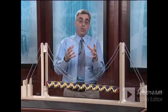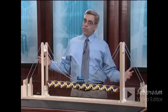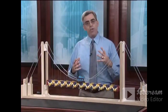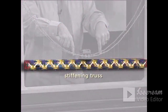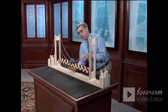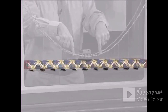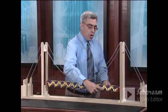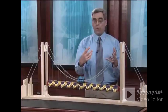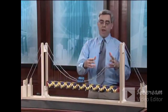The way we look at a structural system is to start at the load and to follow the transmission of load from its point of application all the way out to the structural foundations. So here we have our load, the vehicle that's crossing the bridge, and it's being supported directly by the stiffening truss, one of our 6 basic types of structural elements. Down below, the stiffening truss is supported on a series of transverse beams that run across the bridge. Beams, of course, are another of the element types that carry load in flexure. Each beam is supported by a pair of thin cables called suspenders that go from the beam up to the main cable. So the suspenders are tension members which transmit the load up to the main load-carrying elements, the cables.